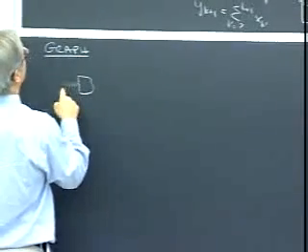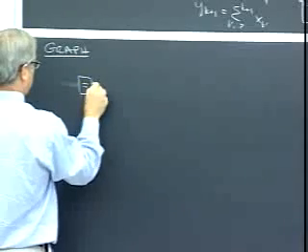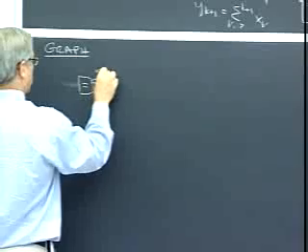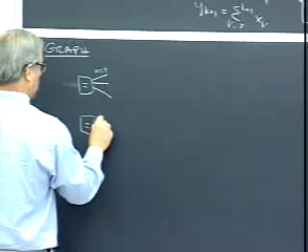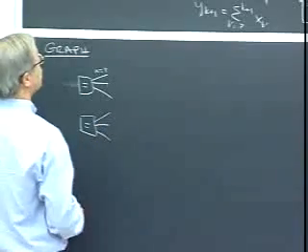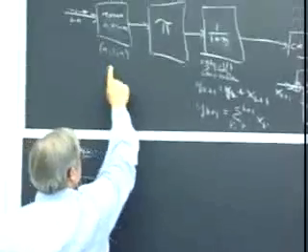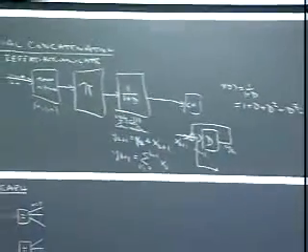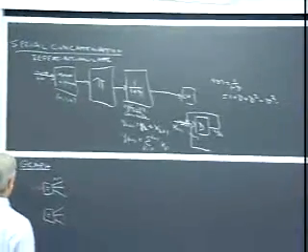The input bits aren't actually part of the output in this case, so I won't draw the dongle. We just have an equals sign with, call it n equals 3, repetition from each bit. What's the overall rate of this code? Here we have a rate 1 over n code. We don't do anything to the rate here, so the overall rate is 1 over n. All right, so let's take a rate 1/3.